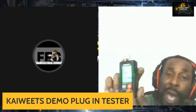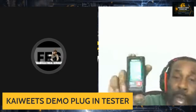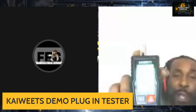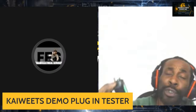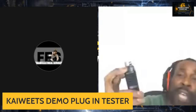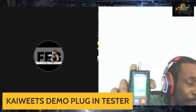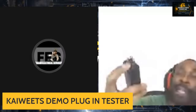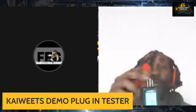When you turn this tester on, you're going to have voltage here. This is the screen where you're going to have your voltage and so on. It also shows open. It tells you if it's an open line, if your neutral is open. So it tells you everything here. To use this properly, your panel cover has to be off, obviously with the proper safety gear on.